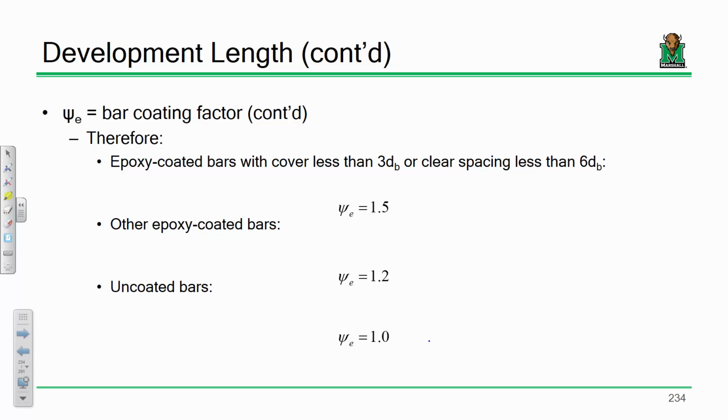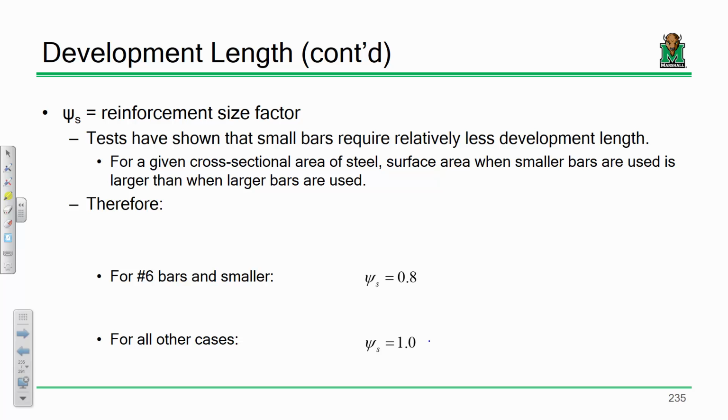And that's one of the things that we're going to find in this development length discussion: it's one big question. It's like, what if you don't have enough room? What if you need 72 inches of embedment and you don't have 72 inches? There's a lot of different adjustments and a lot of different tweaks that you can make to your design in order to affect that. So that'll be an evolving discussion throughout this concept.